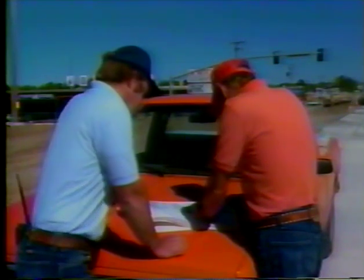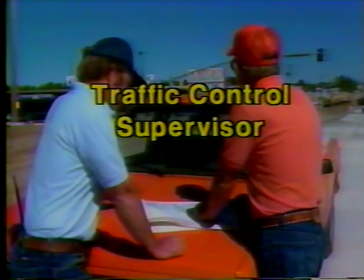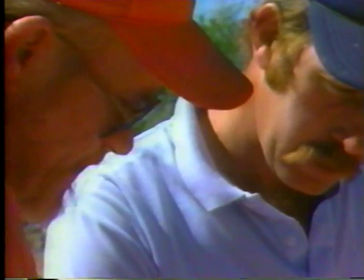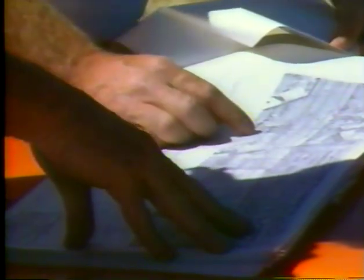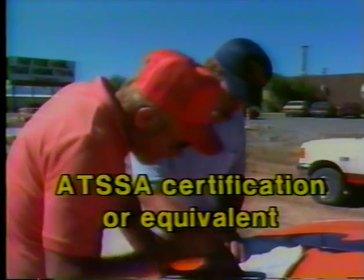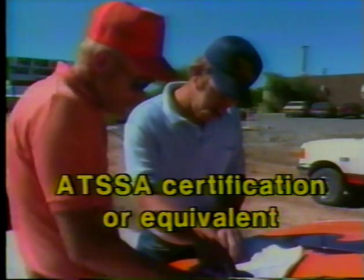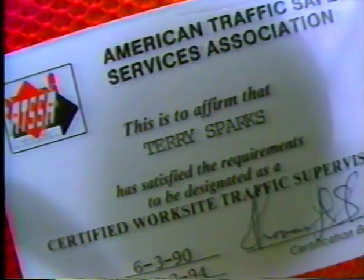In response to this principle, many agencies require the contractor to appoint a traffic control supervisor to oversee project traffic operations. This person must be well trained and able to make traffic control decisions without consulting with his or her supervisor. Some agencies further require the traffic supervisor to be certified by the American Traffic Safety Services Association or to hold an equivalent certification. If that's the case, you should make sure the traffic supervisor's credentials are up to date.